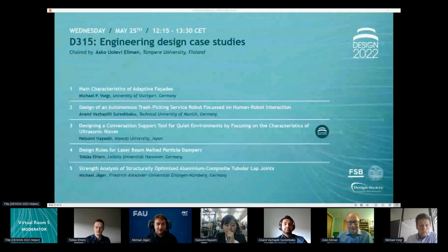Yeah, that's one of our suggestions at the end, that we need to take these material parameters into account. This model is based on two materials with a different stiffness, but they are consistent along the thickness. If you have a layered CFRP tube, you have different stiffnesses in different layers. If you're using laminate theory, you have a resulting stiffness, one E-module, but you have to consider these different sites.